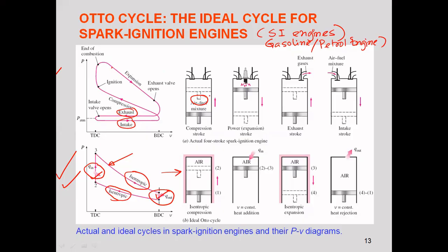So inside, what is happening is represented by these cycles. The pressure or volume here is the pressure or volume of the system itself. Inside this system, when the piston is moving down, a suction is created, that is, a vacuum is created, and therefore the pressure is subatmospheric, and that is the pressure differential. So the inside pressure is less than the atmosphere, and outside the pressure is atmospheric pressure.